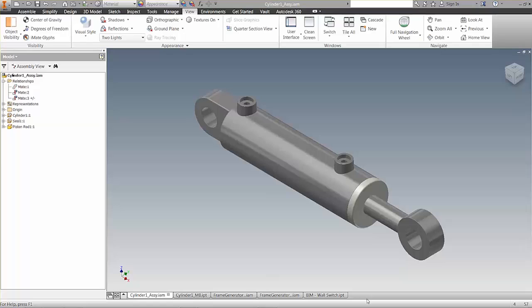The advent of multibody modeling has led to top-down modeling, allowing us to create the big picture first, digging down into the smaller aspects later, and creating the detail. Multibody modeling allows us to model the entirety of an assembly in one part file, creating relationships and dependencies which make the part flexible and adjustable. This leads to easily adjustable assemblies, as multi-body parts can be exploded into multiple parts, which drop into assemblies and sub-assemblies.